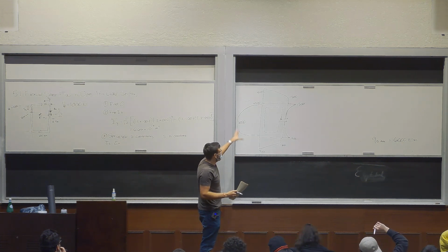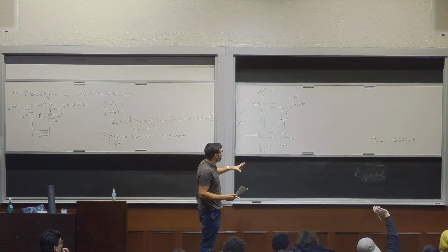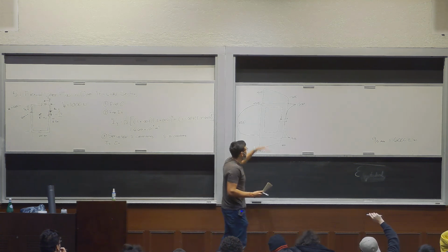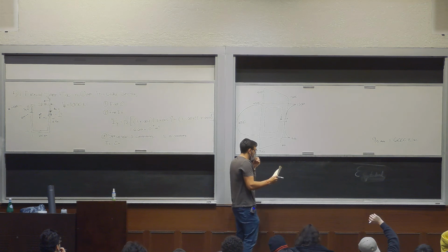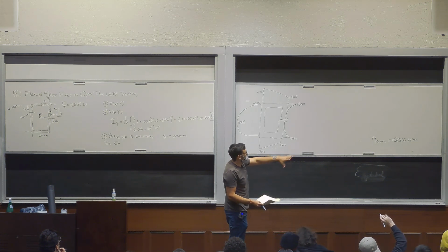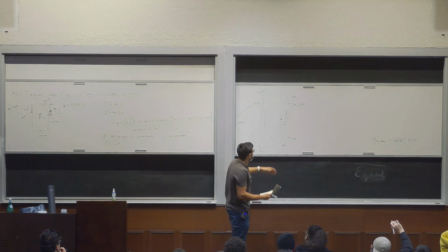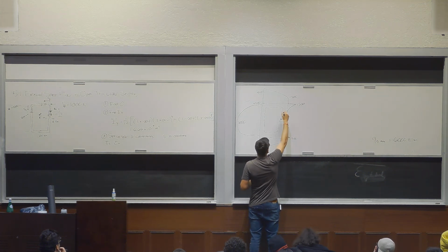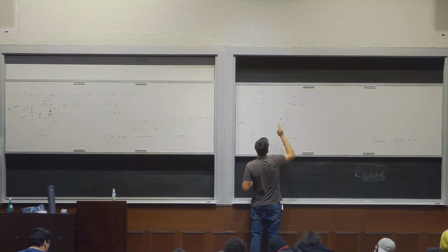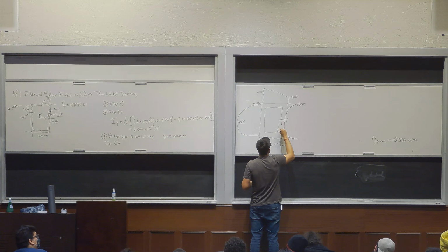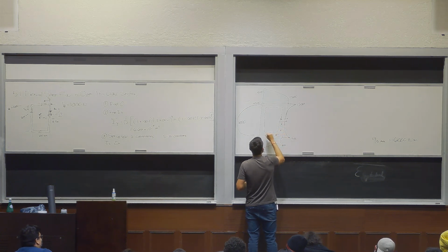Remember, these diagrams here have nothing to do with the direction of the force applied or anything like that. It's just showing the magnitude and how it changes along the length of the structure. And now what direction it's acting in, we got all these negative numbers, right? We had defined the S dimension to be positive in that direction, but we got all negative numbers, so we know that the shear flow has to be pointing like this.